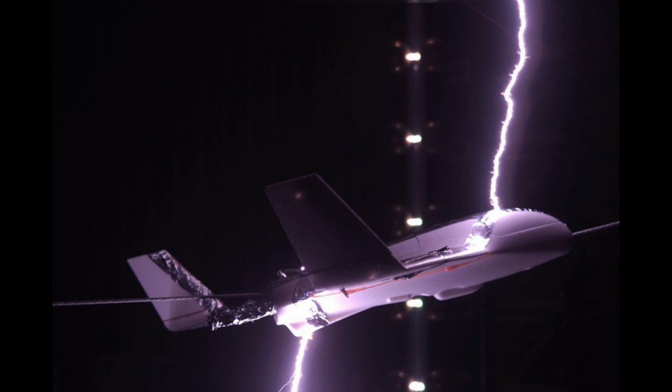If lightning strikes an aluminum airplane, the electrical energy naturally conducts easily through the aluminum structure. The challenge is to keep the energy out of avionics, fuel systems, etc., until it can be safely conducted overboard. The outer skin of the aircraft is the path of least resistance.